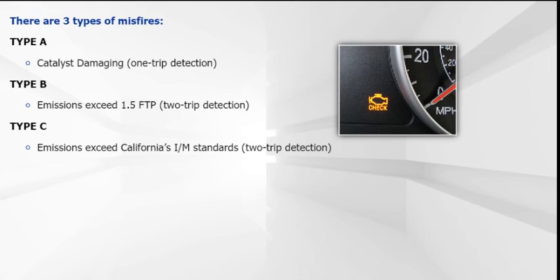Type B and C misfires are generally the result of a fuel control or EGR problem. There are 13 generic DTCs assigned to misfire detection. Depending on the application, the PCM will either store a DTC for each misfiring cylinder, up to 12 cylinders, P0301 through P0312, or simply store a P0300. This code indicates that a random or multiple cylinder misfire has been detected, which typically indicates that the misfire is not specific to a cylinder, but related to ignition components common to multiple cylinders.